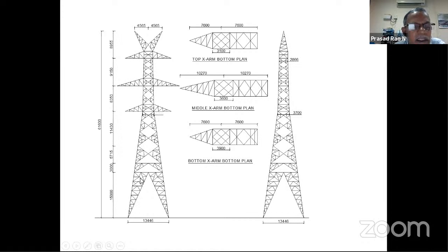That means 12 meters plus 3 meter body extension. One leg will be sitting at a lower level, and the other leg will not have 12 meters, it will have only 9 meters. About a 3 meter difference in ground level is there. One leg will have 12 meter extension, the other leg will have 9 meters. But testing will be done with the maximum leg extension in order to have a maximum effect.